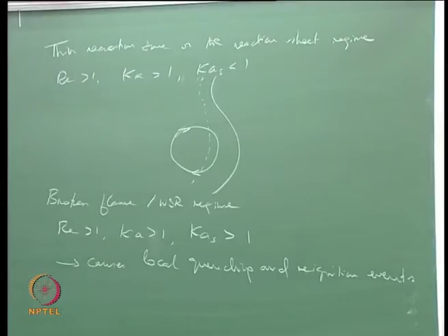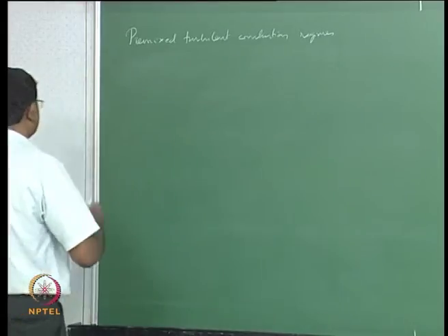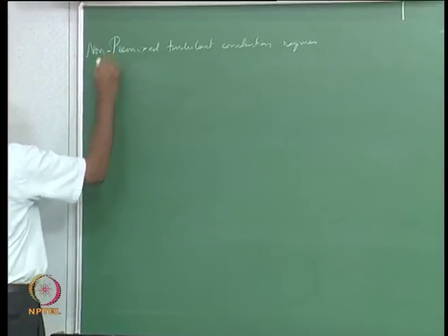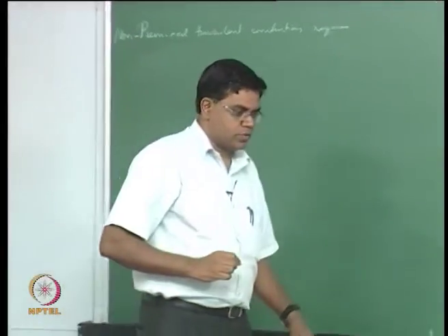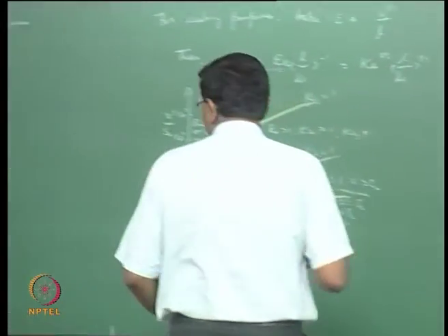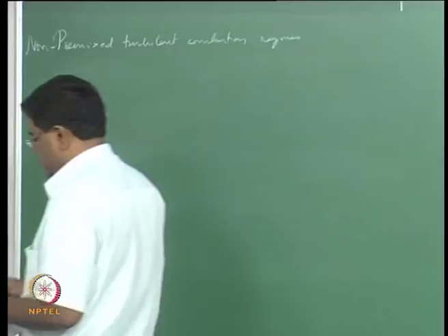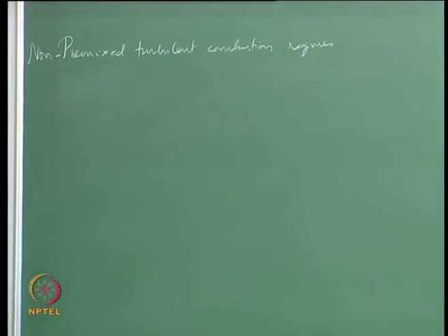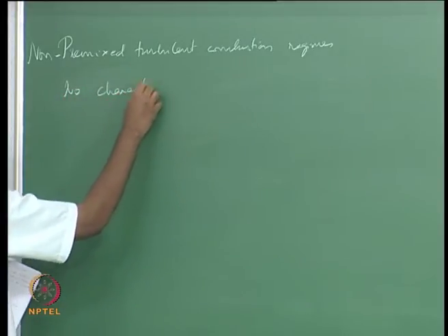Let's now talk a little bit about non-premix combustion. Non-premix turbulent flames, I'm following Peters here, and there is more work that's been done in the more recent past, but I'm not covering that material as far as this is concerned. Now the problem with non-premix combustion regimes is we don't have a characteristic flame speed here.